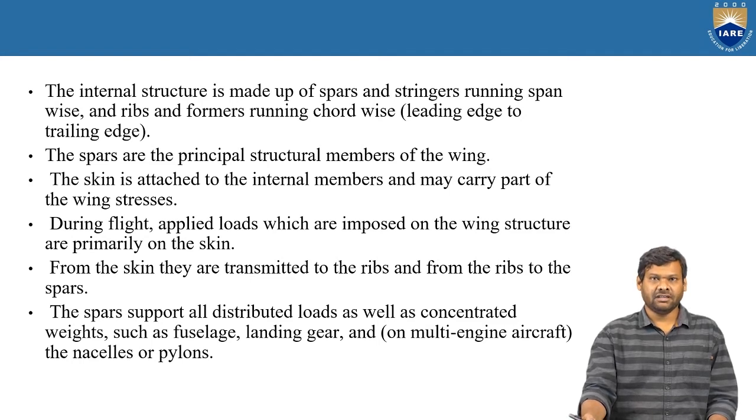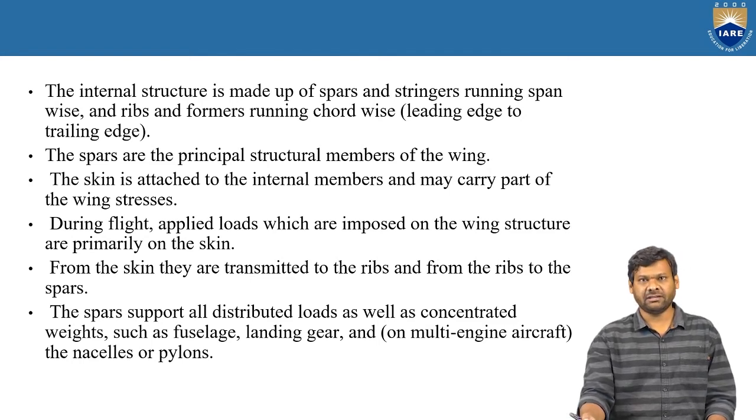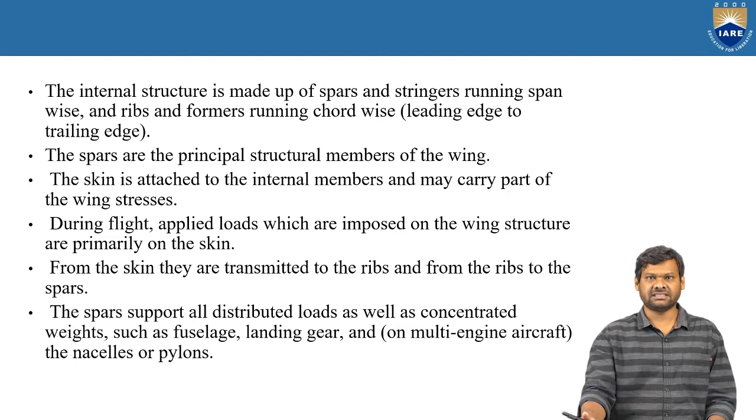For example, when there is an aerodynamic load or when there is an inertial load, or more generally the lift, it is produced on the skin section, and the load which is carried by the skin is transferred to the ribs and to the spars and the stringers.